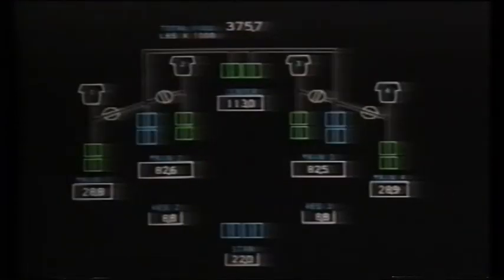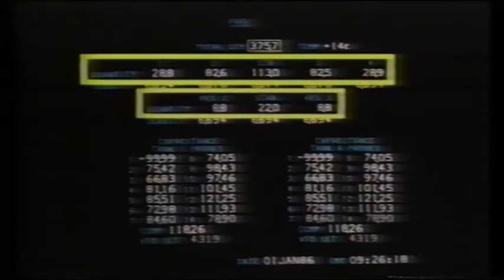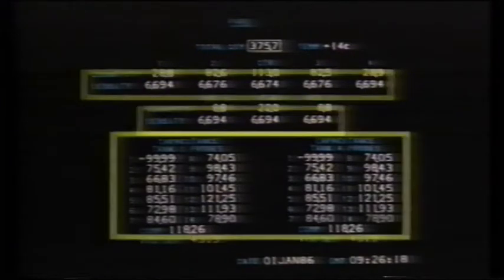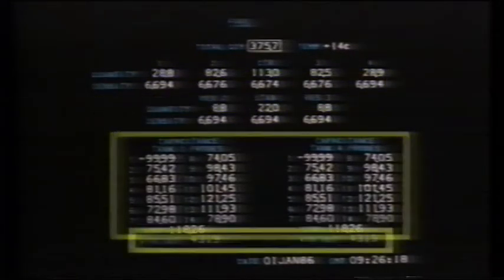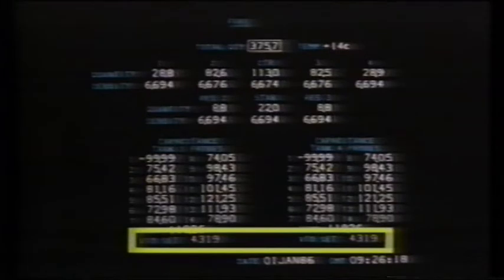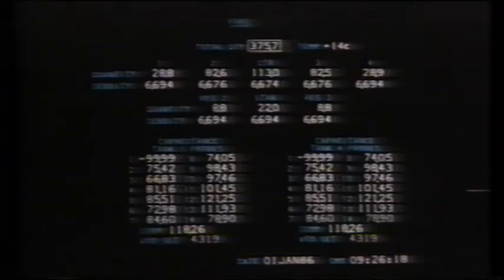Fuel system configuration and individual tank quantities show on the auxiliary ICAS fuel synoptic display. The fuel system ICAS maintenance pages show specific maintenance information for each tank, such as quantity, density, probe capacitance, and volumetric top-off settings. This information shows for one pair of fuel tanks at a time.